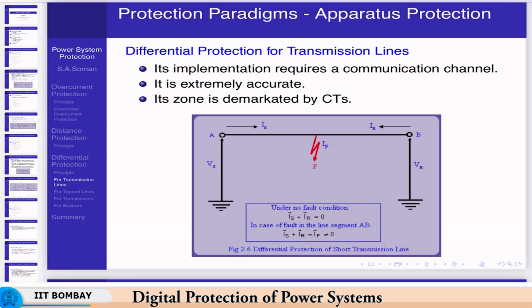But here, for the sake of this discussion, we will consider it as a lumped parameter. We are ignoring the shunt capacitances, in other words, we are ignoring the charging current of the line. That can be incorporated later when we discuss it in greater detail, and then we will see how to overcome any difficulties that are presented by introducing that quantity.